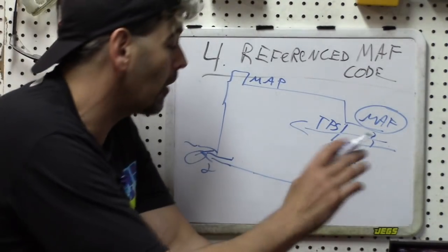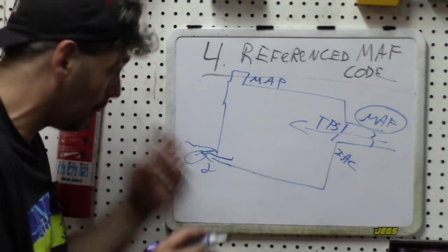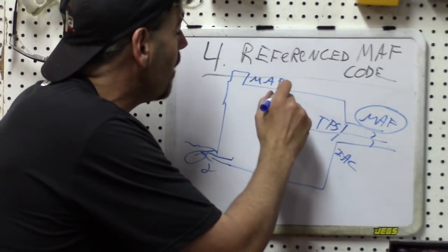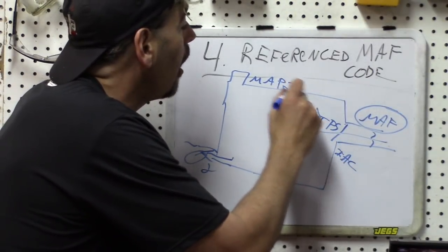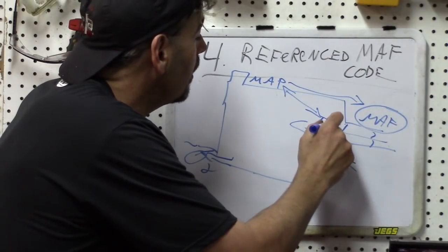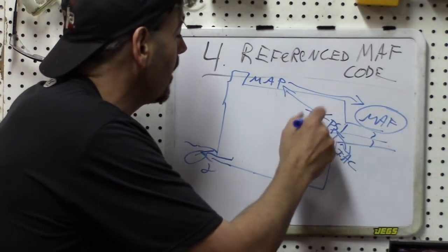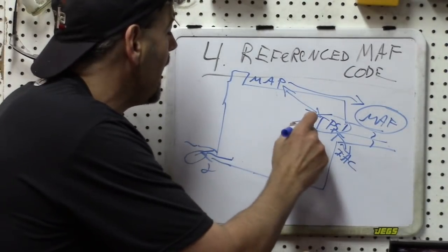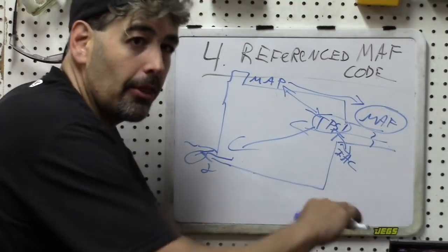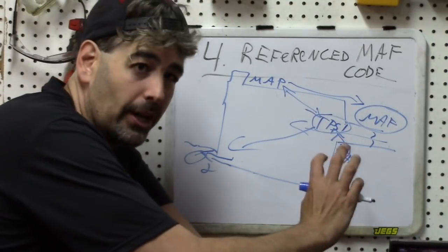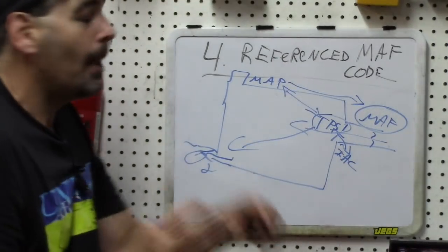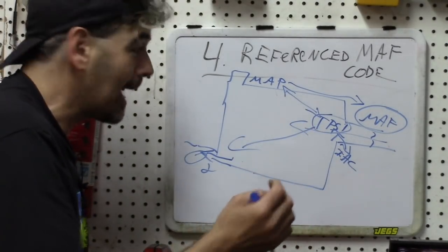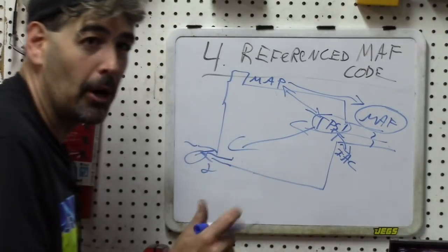So it's very important, and as a final thing for this video and for this series, to show that when you have an error code on any of these components, particularly the throttle position sensor as your main initiating one, you can get error codes on any other air induction related component that is referenced, because whatever your problem is, it's not something that the computer recognizes as being a fault with that component.